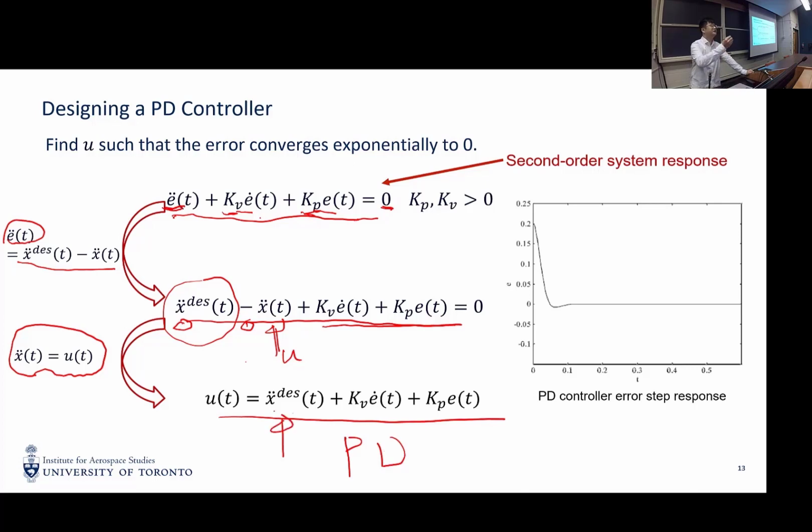If you want your point mass to do some kind of acceleration and deceleration, then you need some kind of feed forward force. That's kind of an equilibrium force. In addition to that, if the point mass moves away from the equilibrium you designed, then e dot and e will be non-zero. Those additional errors will contribute as additional force to drive the system back to the desired trajectory.